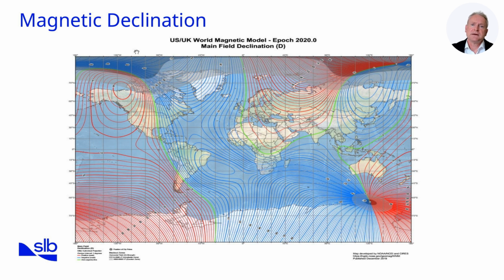Okay, question. If each one of the declination lines on the picture represents 2 degrees of declination and red is positive, approximately what declination is Basra? I will pause a moment for you to look. Right, so Basra is at the bottom of Iraq, at the tip of the Persian Gulf. There is a red declination line that passes through it, which is positive 4 degrees.